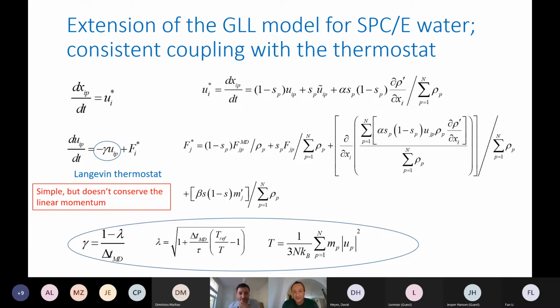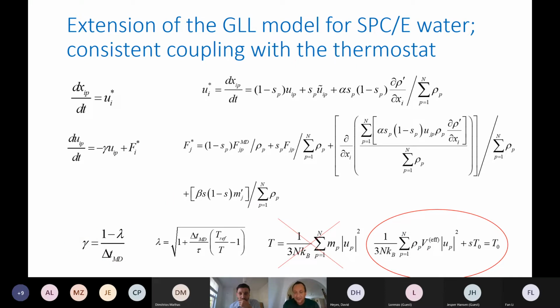So hence what we had to do at the time is to adjust the thermostat equations, such as, instead of calculating the temperature as the standard summation of the squares of the velocity in accordance with the equipartitioning theorem, we introduced a model equation based on some effective total enthalpy. So we are essentially adding the energy of the particles and the energy of the continuum with some weights in accordance with the concentration.